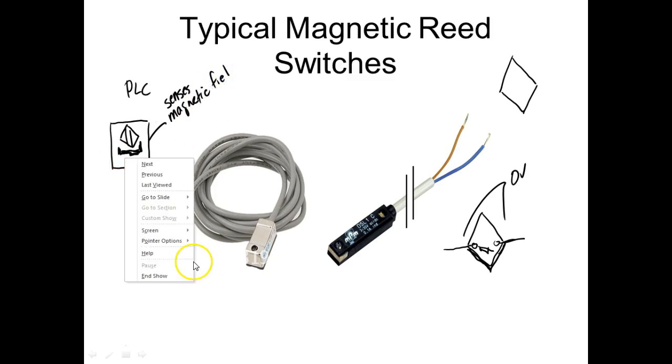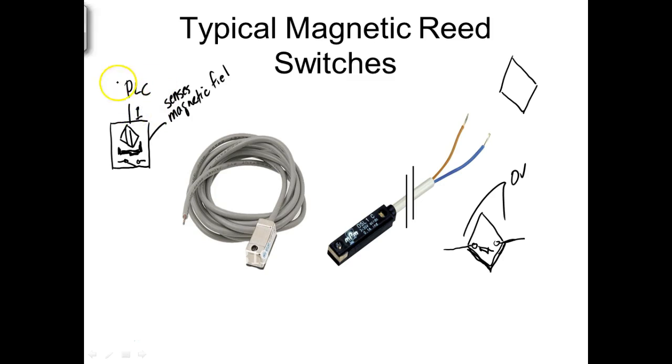And then what we'll do is we'll come below that and put one normally open contact. And then up here, this would be 1. So this is going to go toward L1. And for this sensor, this is going to be 3. And this is going to go toward the load. But that's just for this sensor. We'll have to look at some solid state sensors. This is going to go on DC, this would be plus and this would be minus.